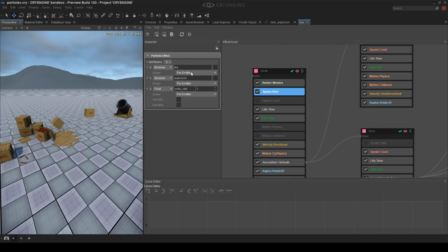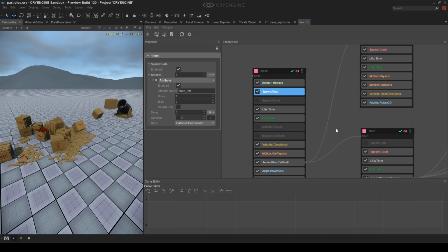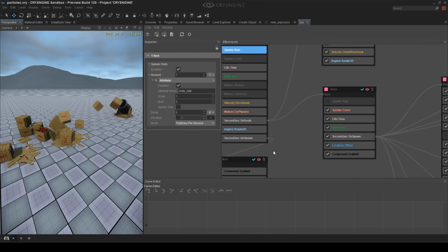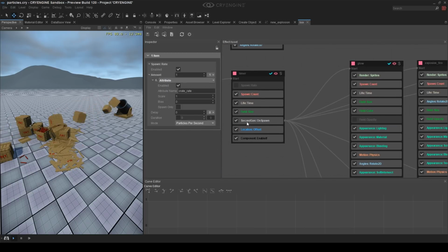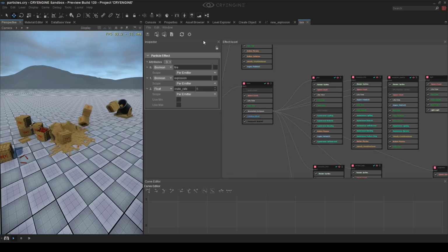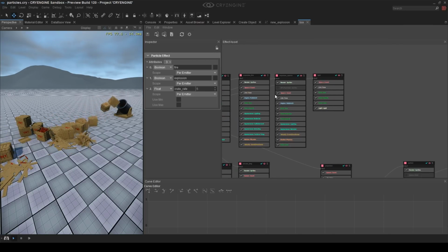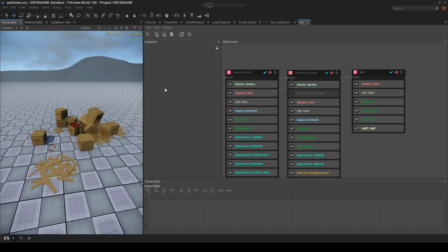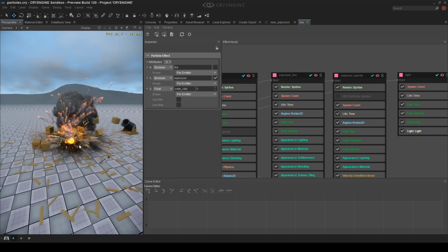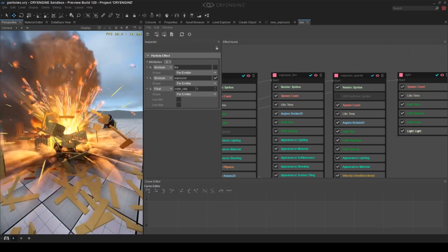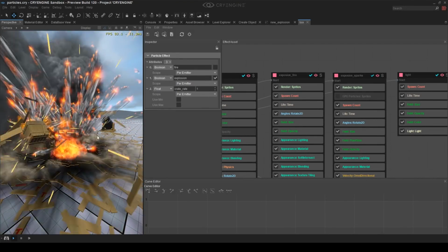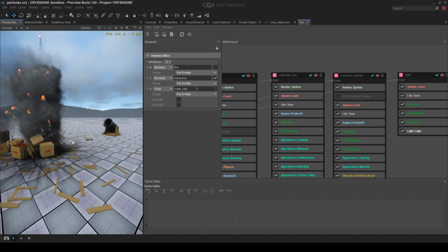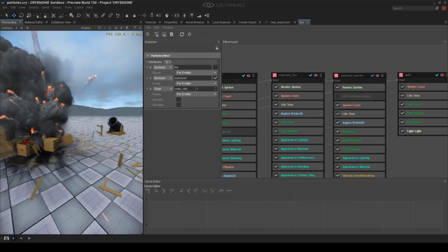So if I go in the create rate here and I just ramp it up to 5, we get 5 times per second. So you don't necessarily need a curve. Now maybe you say, oh, when the rate is so high, I want to reduce some other counts, and you could do that. You could go into the individual parts and have another curve that would just reduce some other pieces of some parts, because maybe this is too much explosion for you and you can't handle it. So you would still have just one value, but then you don't just increase the count on everything. You increase and reduce at the same time to compensate.